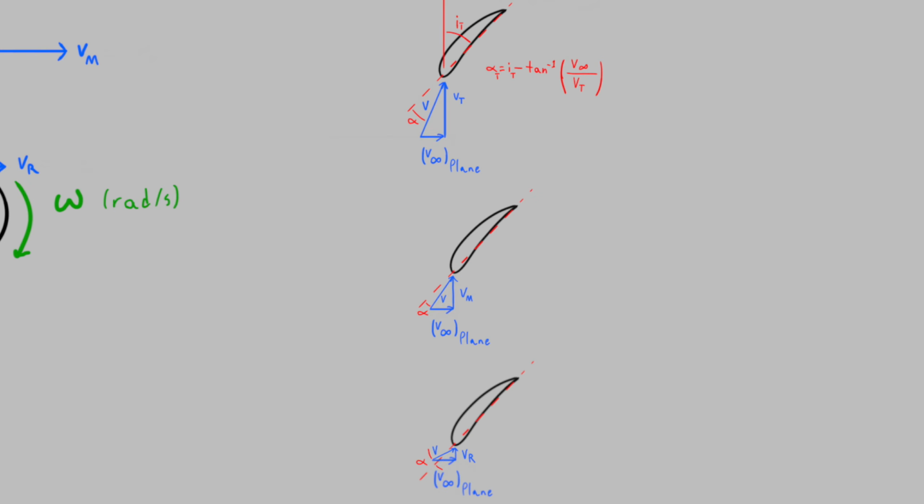By taking the arctangent of these two component vectors, we can calculate the blade's angle of attack at a given RPM, percent span, and airspeed. Fortunately, the game already does all this for us at the root, midsection, and tip in the prop's part window.